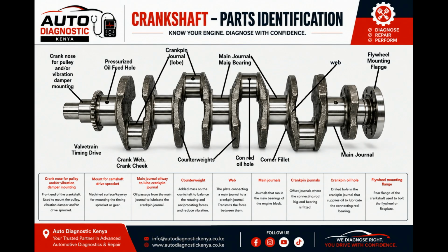The front of the crankshaft also requires an oil seal, and just like with other lip type seals, the sealing lip should be lubricated before the pulley is installed.